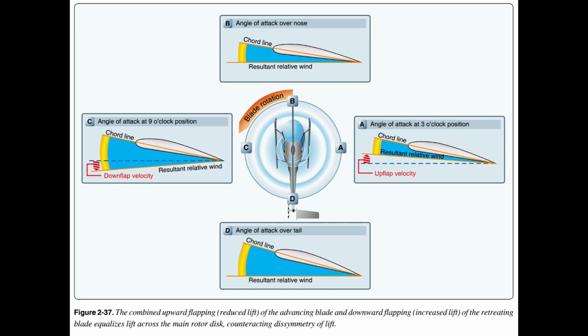When transitioning to forward flight either from a hover or taking off from the ground, pilots must be aware that as the helicopter speed increases, translational lift becomes more effective and causes the nose to rise or pitch up, sometimes referred to as blowback. This tendency is caused by the combined effects of dissymmetry of lift and transverse flow. Pilots must correct for this tendency by maintaining a constant rotor disc attitude that will move the helicopter through the speed range in which blowback occurs.